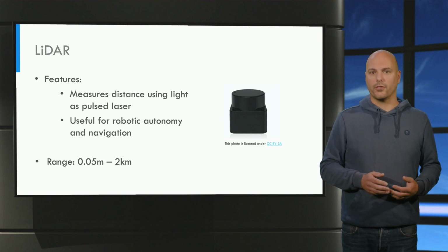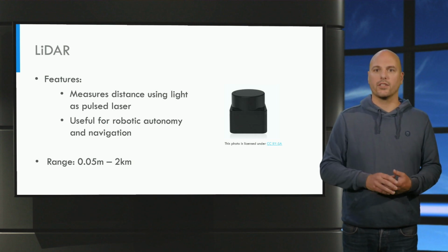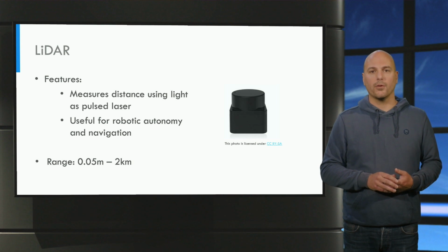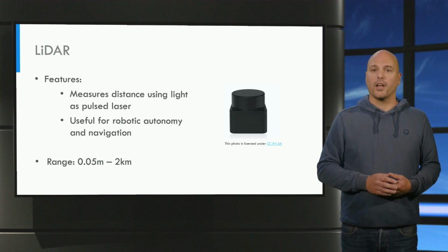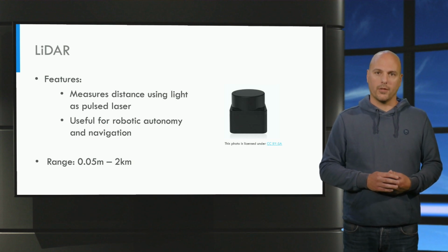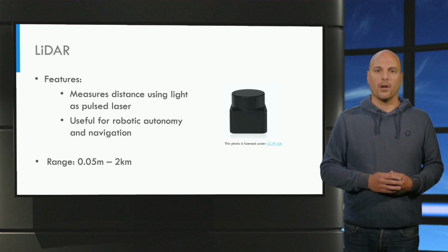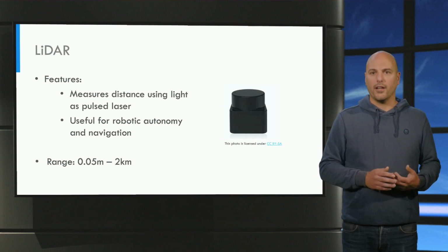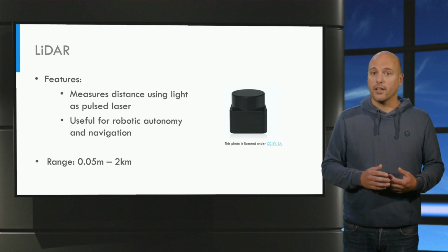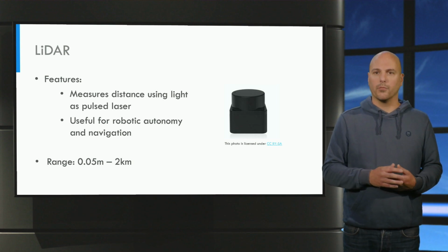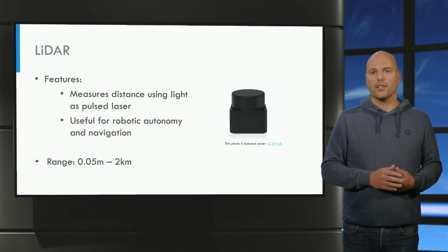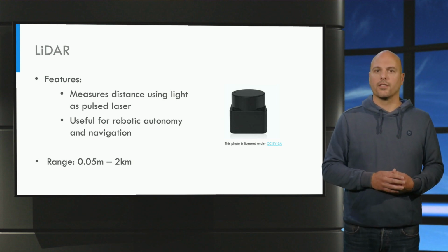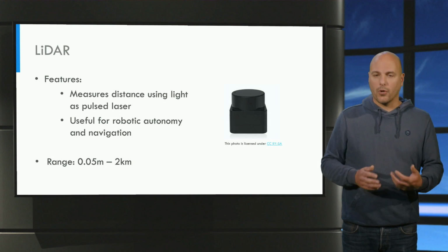More commonly used are LiDARs scanning a plane in 360 degrees by rotating the LiDAR beam. This can generate a map of the environment. An even more complex LiDAR might also tilt the beam, creating a 3D image of the surroundings. A LiDAR works great on any material reflecting light. Black surfaces, mirrors and glass can produce errors. Modern LiDARs use solid-state technologies, not using rotating parts anymore.